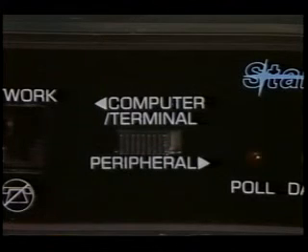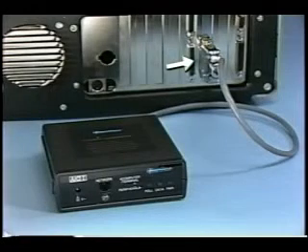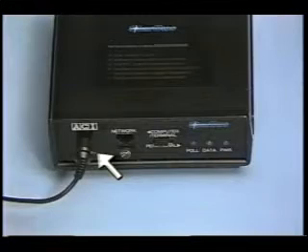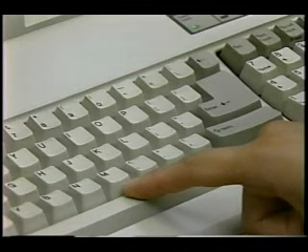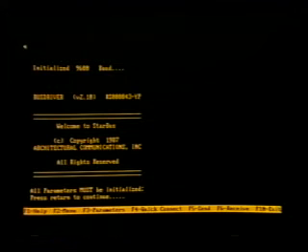Check that the panel switch on the bus driver is set to the left. Plug the power pack into the wall. Plug the RS-232 cable on StarBus into the serial port. Now, while holding down the space bar, insert the other end of the power supply into the bus driver. This sends a stream of space bars into the bus driver, and the bus driver automatically sets its transmission speed to that used by your computer or terminal.